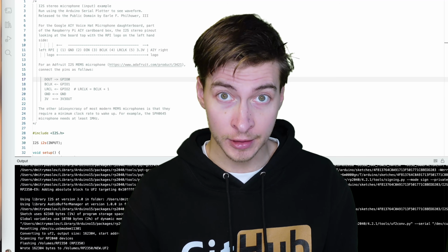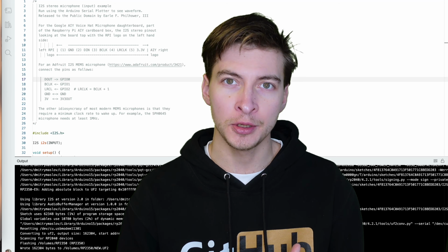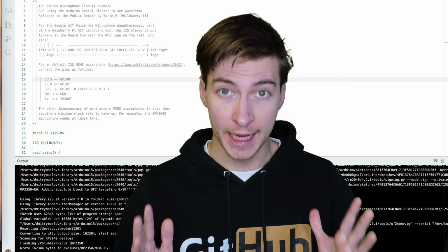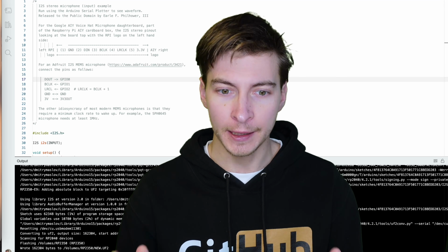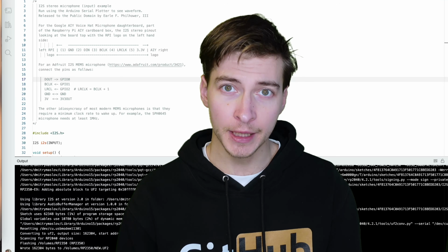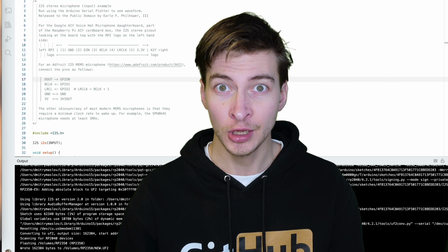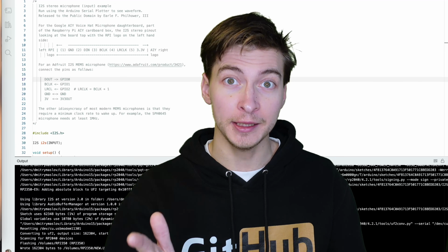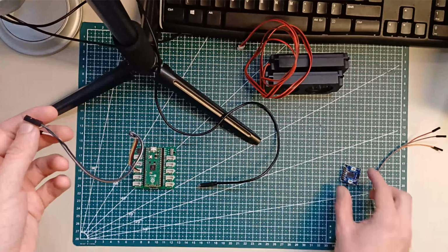and not something fun and useful like recording and playing the audio or recording into a WAV file? Well, when starting out with new hardware, it's important to have as few points of failure as possible. If your code is that simple and you know it works, if something goes wrong, you know it's either wiring or the hardware. If you screw up the code but don't know about it, you might be tempted to look for a hardware issue when it's not really there, and vice versa. So, start simple.